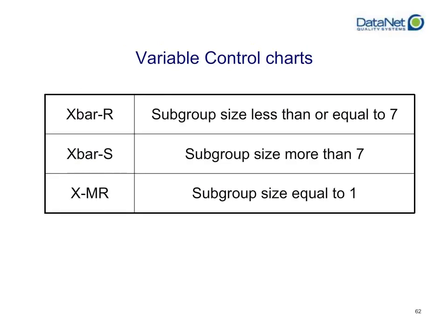Now, if you recall from the previous slide, we started talking about the different valid control charts that you could have for either variables or attributes. We will cover a little more in depth the different possible valid variable control charts, or at least the very common ones. The Xbar and R chart is probably the most common chart. It is used anytime you have a subgroup size larger than 1. You tend to use it when the subgroup size is also smaller than or equal to 7.